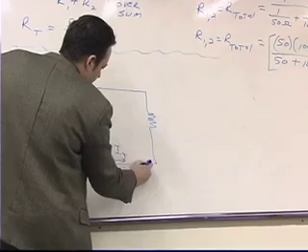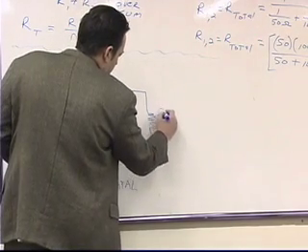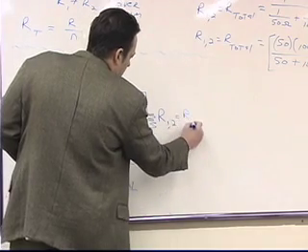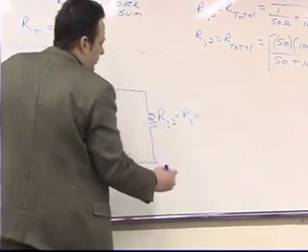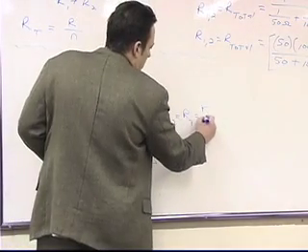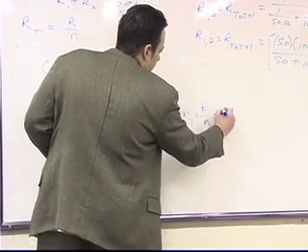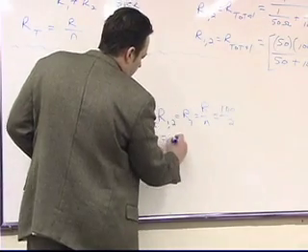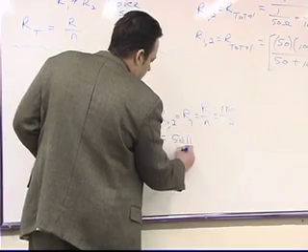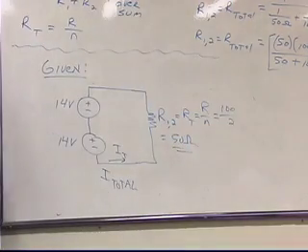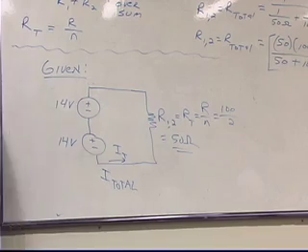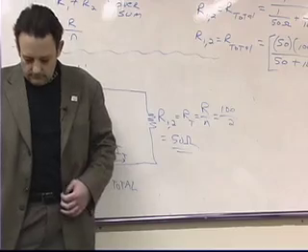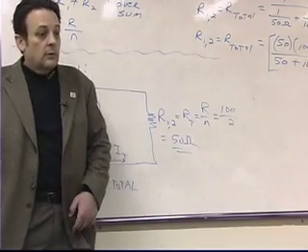So if I combine this into one resistor, I'd call it R1,2, which is the same thing as R total, which would be equal to R over N, which is the same thing as 100 over 2, which is the same thing as 50 ohms, right? Okay, now what's the next thing that I have to do? Voltage over resistance. I equals U over R.